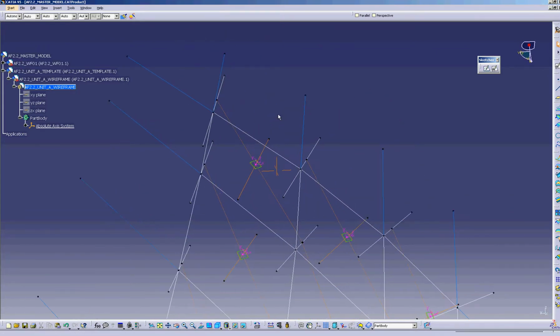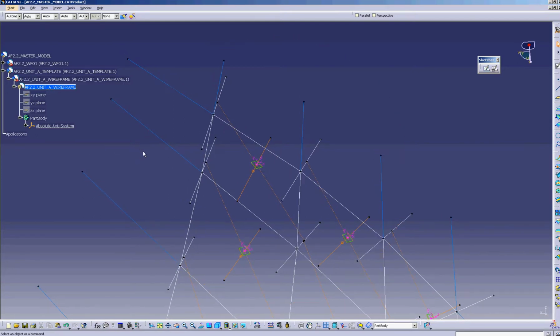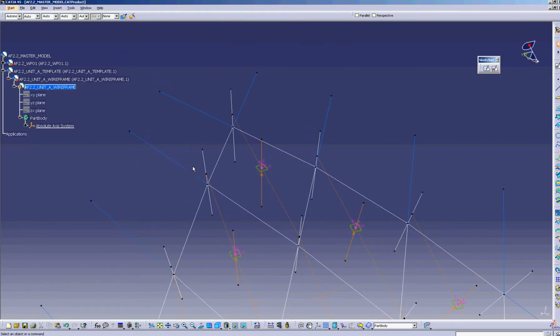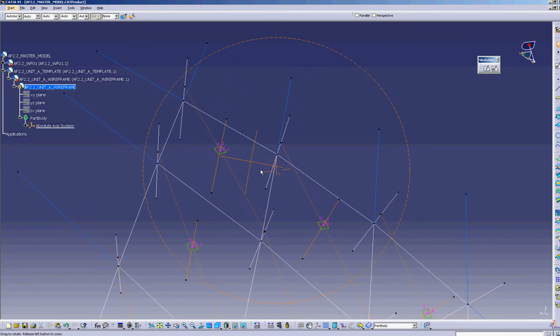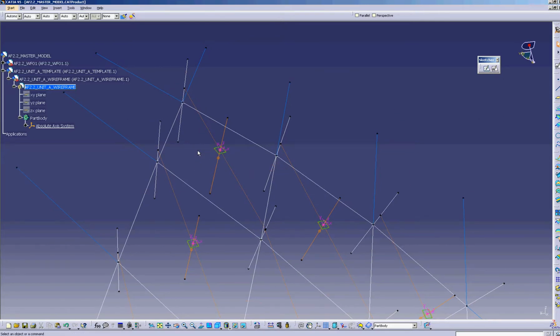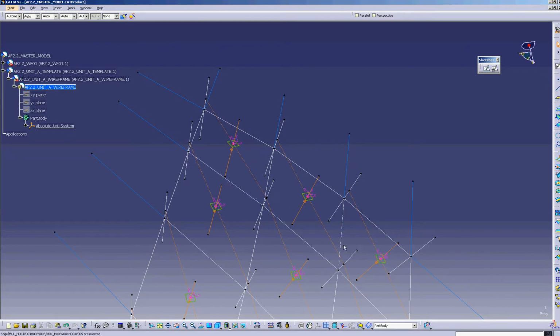Let's zoom in on this wireframe. And we have to figure out now, as a designer, oftentimes when you get to this level in a project, you've already designed the details and what you want the system to do. So we wouldn't be making this stuff up on the fly. But today we are. So just to illustrate the concepts here, what we're going to want to control is the offset. We're going to create an offset of these edges inward from this, on the level of this plane, and we're going to say that that is controlled locally at the level of the panel. For some reason, we'd want that to be different for every panel.